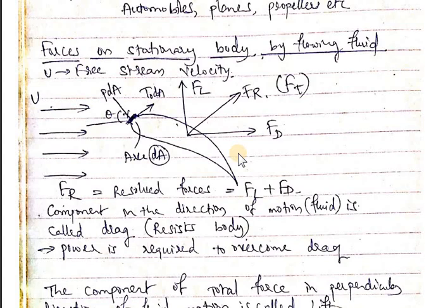And nowadays if you see the vehicles, the front shape or the body design of the vehicles is many times designed with aerofoil shapes. But in earlier days the truck or bus shapes were completely flat bodies, which are also called bluff bodies. So in that situation we have to consider the aerofoil shape as a general case to discuss the forces. Now as the air approaches the entire aerofoil shape, as usual for derivations we consider a small area, and later we are going to integrate the small area into the full area to resolve into different forces.